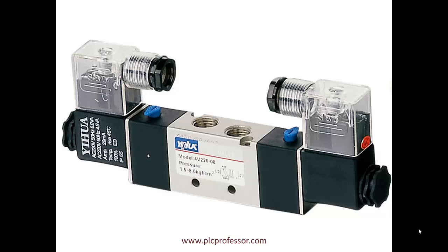Inside of that valve body is a spool. It's a long rod with concentric grooves machined into it, and as the spool shifts back and forth, it connects the ports from one side of the valve body to the other to allow air pressure to flow in the direction that we want.